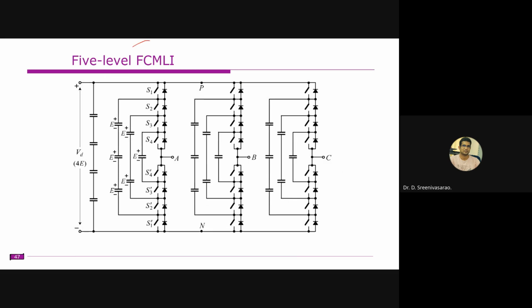This is another thing, which is the flying capacitor multi-level inverter. This is much less popular, but hybridization of this one is slightly more so. We have some applications in the traction drive. It consists of some pre-charged capacitors. Right, these are some pre-charged capacitors here. These capacitors produce some voltage levels, and this is especially advantageous in applications like traction applications.